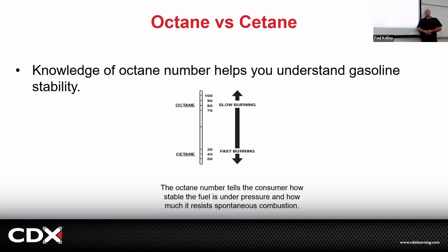The ethanol has a different octane rating. So it can be somewhat beneficial because we can get our octane level a little bit higher using some ethanol. So ethanol does have a much higher octane rating. That's part of the reason you'll see these crazy race cars running E85 with huge turbos and tons of ignition timing, very advanced, and making a ton of power because, well, gasoline high octane at 91 is the best we could do. You can buy race gas at 100 octane or whatever, but that ethanol is high octane right out of the gate and it's cheap. It doesn't have great range though.